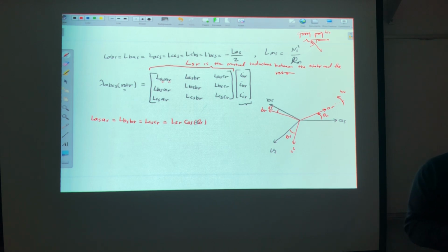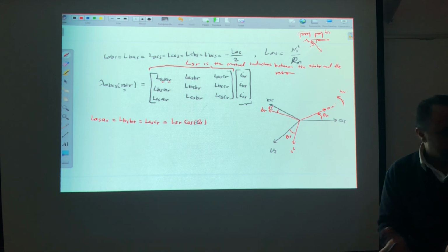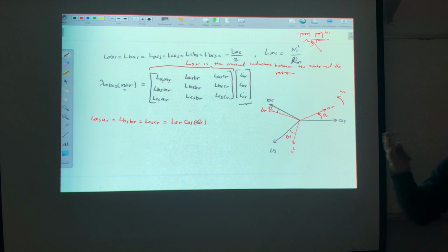Now, the BH curve is the relation between the flux and the current, the flux linkage, or between the flux density and the field intensity. Good. Now, any physical system cannot hold the flux forever. It will be saturated. So, when the flux is saturated, this means that if I increase the current, nothing I can change in the inductance, which means that I'm consuming more power than I need. And I think we discussed that somewhere in the class.